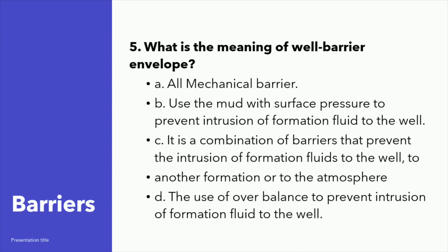Barriers. 5. What is the meaning of well barrier envelope? A. The all mechanical barrier. B. Use the mud with surface pressure to prevent intrusion of formation fluid to the well. C. It is a combination of barriers that prevent the intrusion of formation fluids to the well, to another formation or to the atmosphere. D. The use of overbalance to prevent intrusion of formation fluid to the well. The correct answer is C.